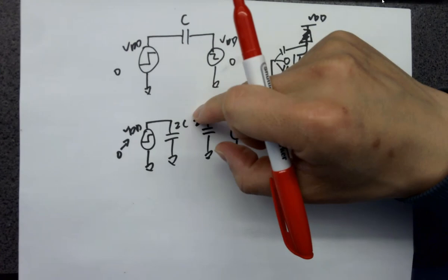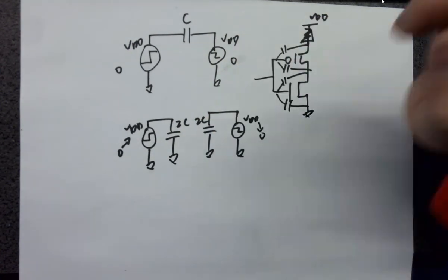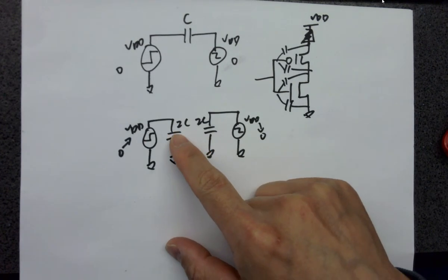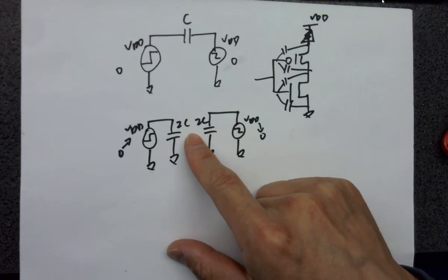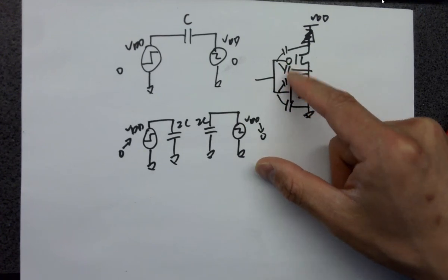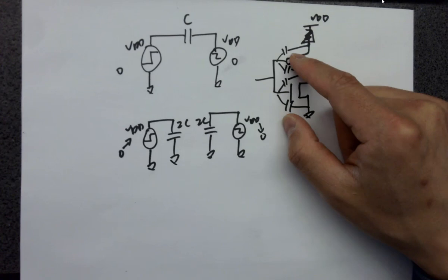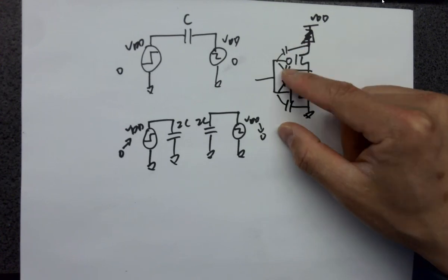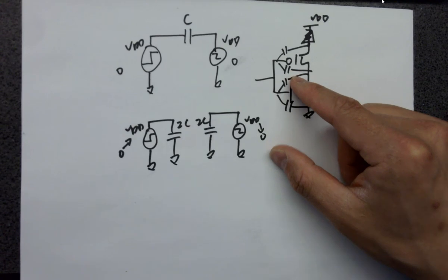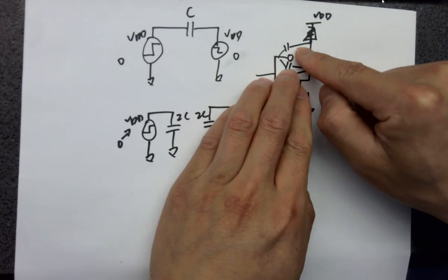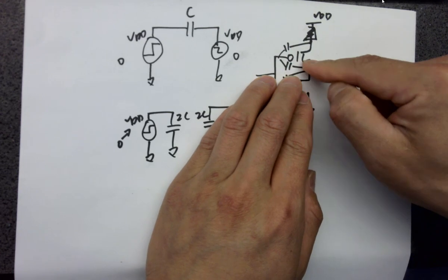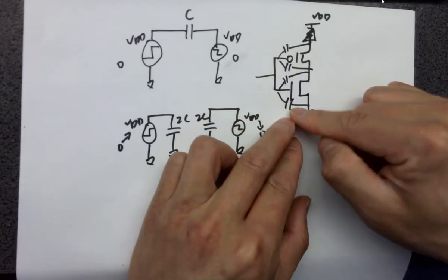So what is the Miller effect? Refer to the notes from last lecture, okay? Because of the Miller effect, we are seeing a bigger input capacitance compared to the real physical capacitance existing underneath the gate. So this is how we model it. If there's no Miller effect, just in theory, these capacitors are basically a half. So this is a half of the COX, and another half of COX. So half COX, half COX.